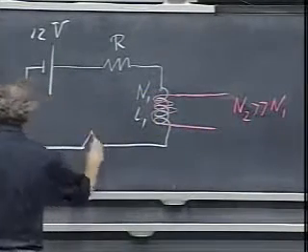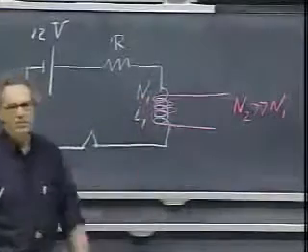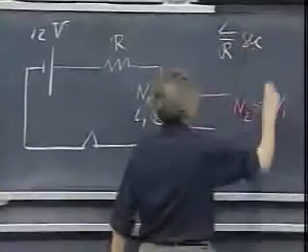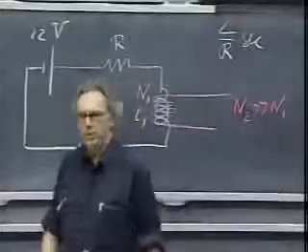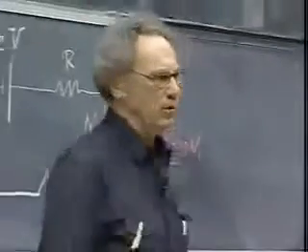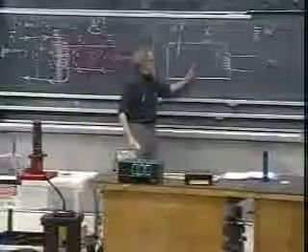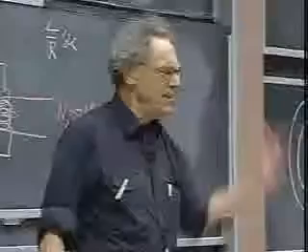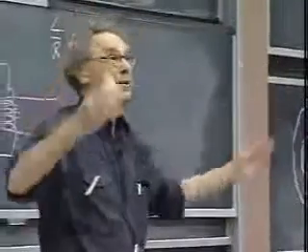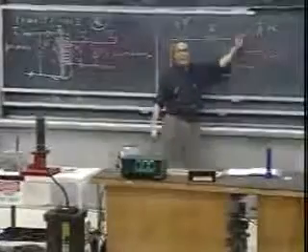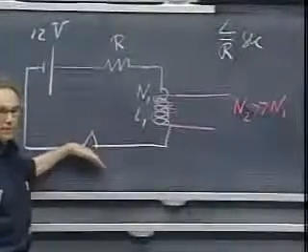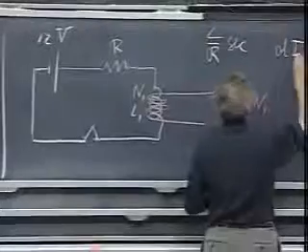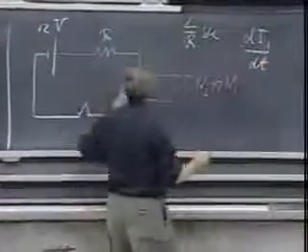I close the switch, a current is going to build up, and the time constant is L over R, seconds. We discussed that before. It's going to build up. And now I'm going to do something extremely cruel. I'm going to open this circuit, open the switch. Imagine what I'm doing. I'm cutting instantaneously the current. The current is going happily, reaches a maximum value after several L over R seconds, and now I open it up. So I get a huge value for dI1 dt. I1 is now the current in the primary.